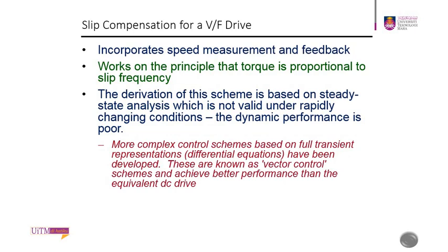Another way to prevent this is by slip compensation. So the V/F drive incorporates a speed measurement. You have sensors for speed measurement and feedback. It works on the principle that the torque is proportional to slip frequency, and the derivation of this scheme is based on a steady state analysis, which is not valid under rapidly changing conditions, and the dynamic performance is very poor.